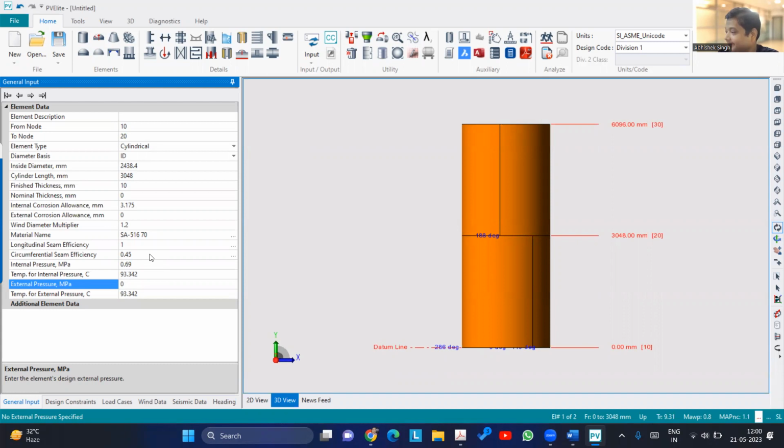Guys, it is not governing. Because circumferential stress is governing, which acts on the long seams. So that is the reason. Even if you have RT2, and RT2 only changes the long seam's efficiency, it will not have an effect.